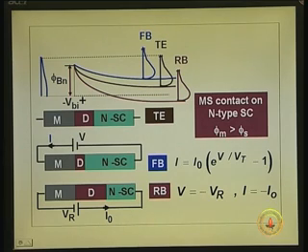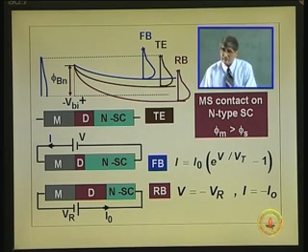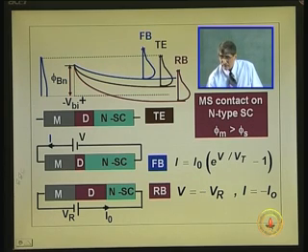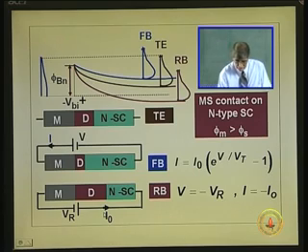We have also seen, and we will in fact derive this and show later, that the I V characteristics of this device is given by the same equation as that of the diode, only the I naught is different compared to the p-n junction. The mechanism of I naught is different, that we will see when we discuss the I V characteristics next in a couple of lectures. Now, for reverse bias, putting V equal to minus V r, that term goes off, you get minus I naught, telling you that the polarity is reversed there. Okay.